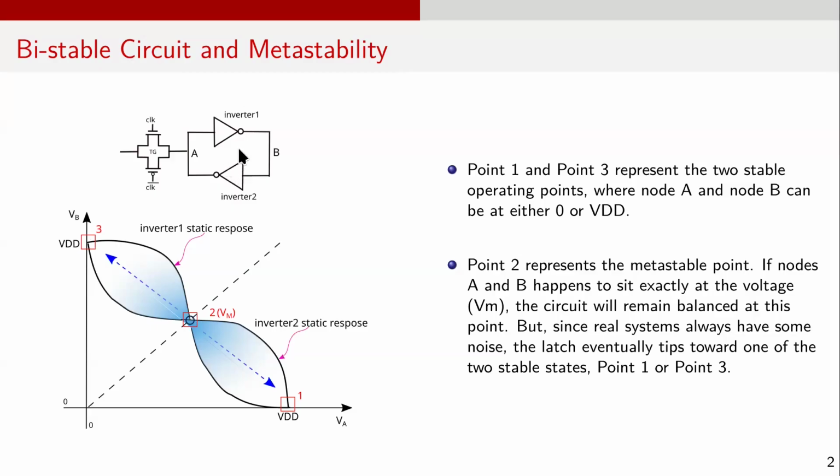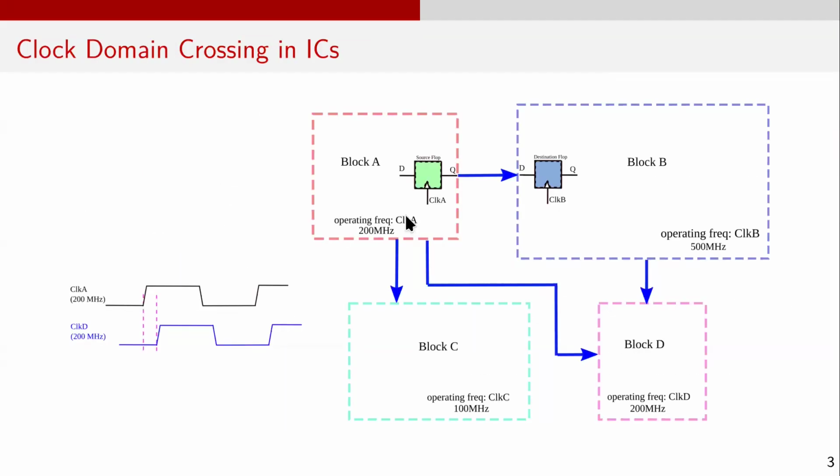Here, we looked at a simple latch. In a master-slave flip-flop, which consists of two latches, the same metastability concept applies to both the master and slave latch.